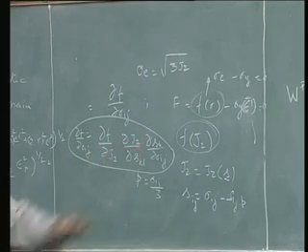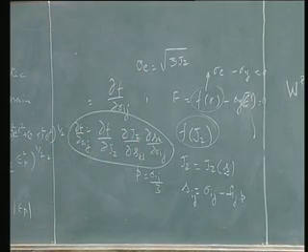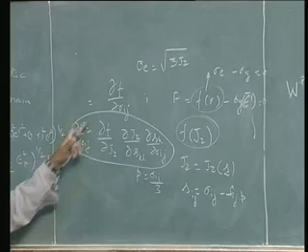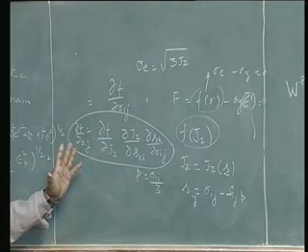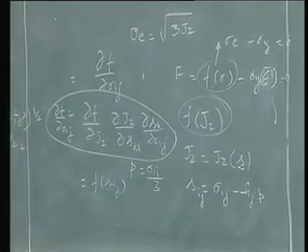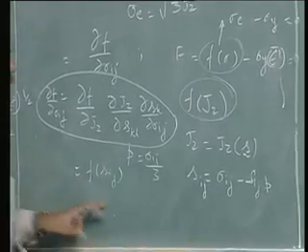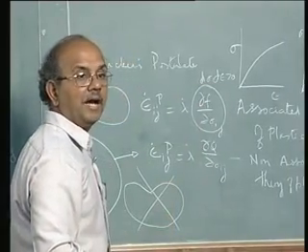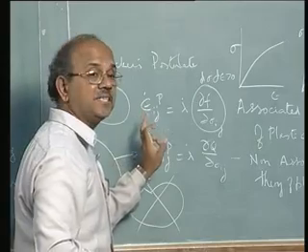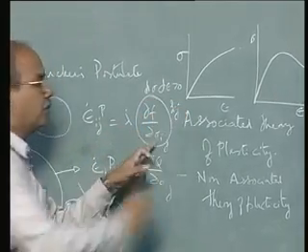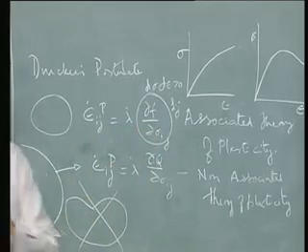So, I have to now differentiate carefully between all these three things and then put them together. So, we will do that in the next class, this derivation, but you will be surprised to find out that this dou f by dou sigma ij will be a function of Sij. In other words, when I substitute it in this form here, I will see that the plastic strain and stress will be coaxial.